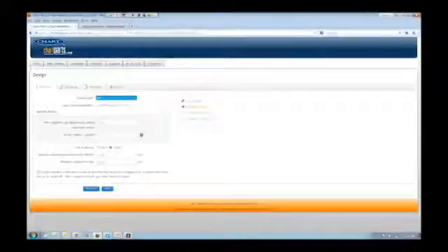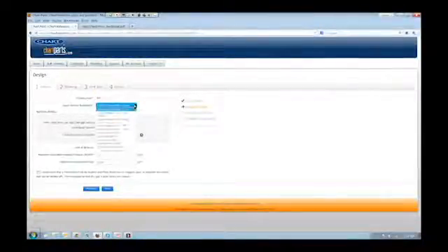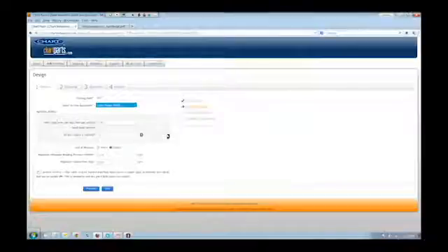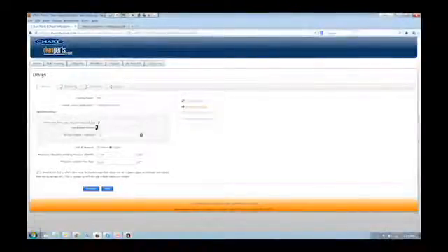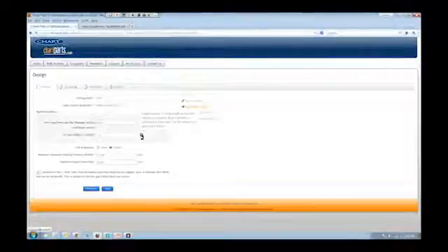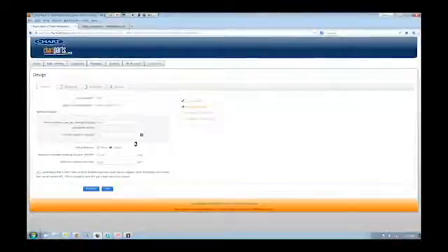or MPT connection. We also ask, what kind of application is it? In this case, it's going to be liquid oxygen. So that helps us understand the application. This system sizing is really about whether you need a cryo vent or not. So how many hours per day are you needing liquid service? There's a little help text here that says, if you need liquid service in 10 seconds or less, you're going to need a cryo vent. So that helps our team to know whether a cryo vent should be in there.